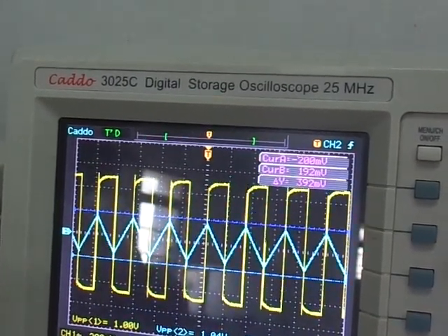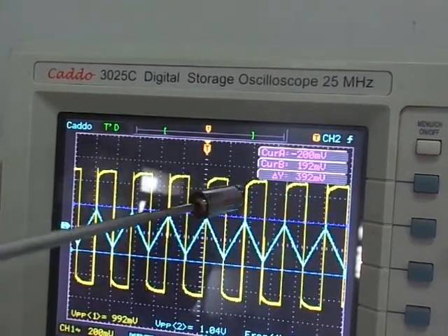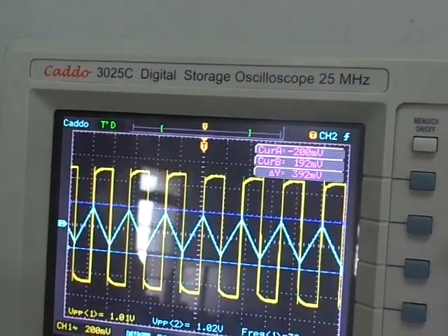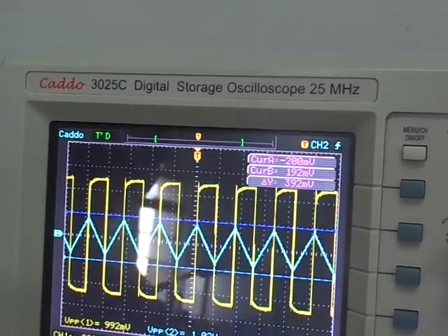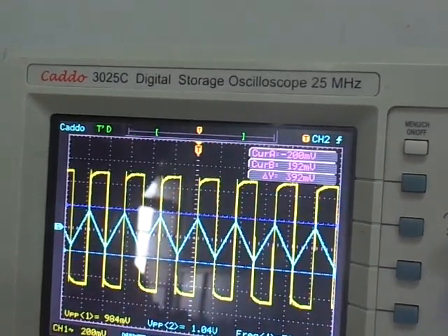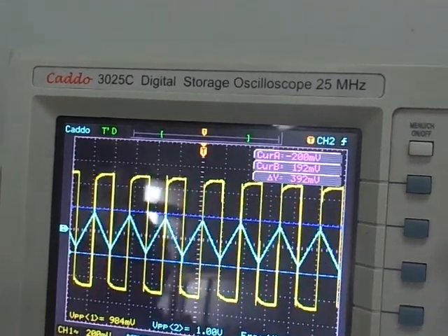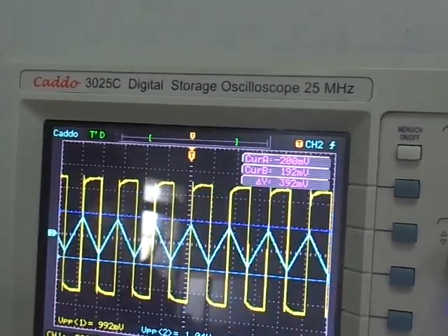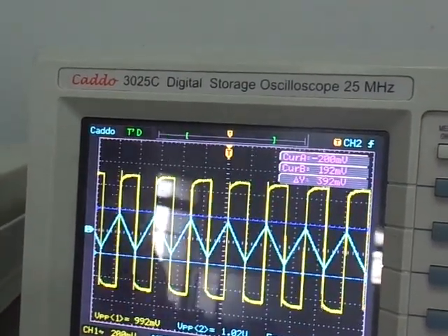The integration takes place. We have achieved the input waveform here, input waveform in yellow color and blue waveform as the output signal. Here the output waveform, that is blue, is a triangular, and here at 20 kHz the value is 1 volt, means FB we have obtained. We have designed FB as 16 kHz, 15.9 kHz, and practically we are getting 20 kHz.